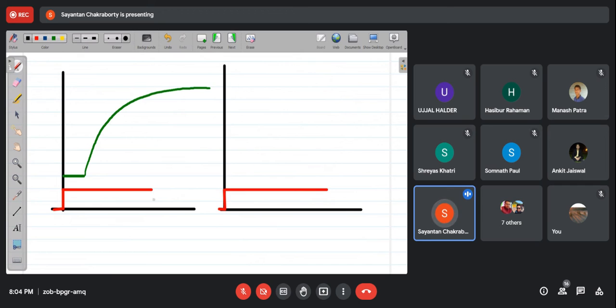If you look at the time scale, suppose the step change has occurred at 0, it has started to react after some period like this, and then it reaches steady state after, say, 5 hours. So shall we wait for 5 hours to obtain the model? Is it advisable? Let us put some values. Suppose your initial value of the input was 2.705, and there's a step change to a value 2.715, and the output response corresponding to that changes from 99 to 99.8. So from that, you obtain the transfer function.